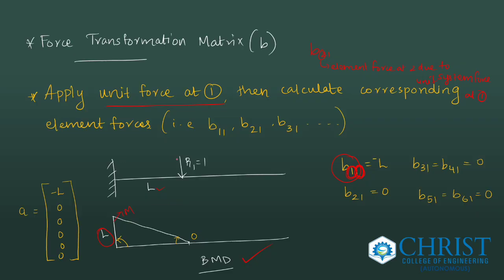This load will produce a clockwise moment and an anti-clockwise moment is developed here, that is L. So its direction is anti-clockwise, hence it is shown here. You can just draw the line from the baseline to the bending moment. So it is anti-clockwise and hence we give a negative sign, minus L.